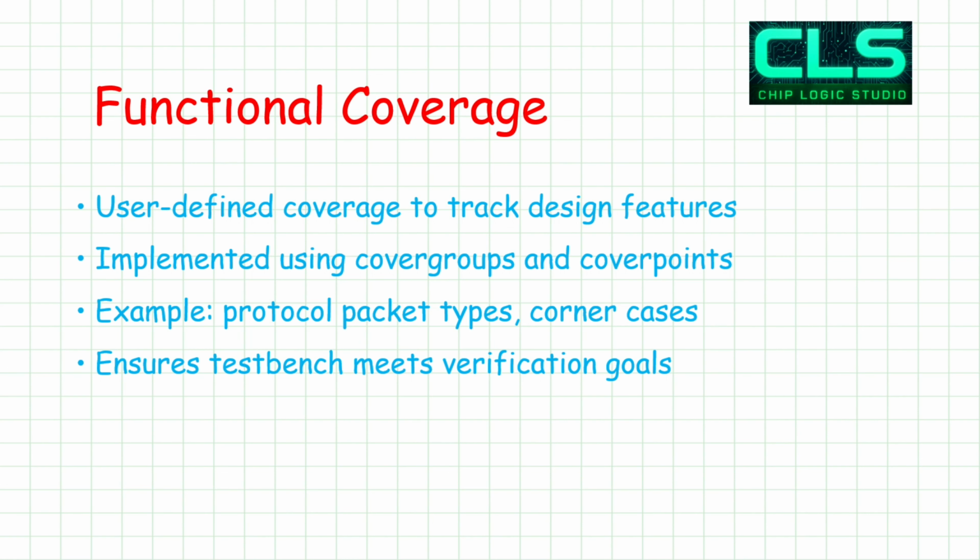All of the packets we send towards our design through our test case scenarios are then checked by our functional coverage to see whether they are covered or not. Also, the test bench meets verification goals. So some set of goals are there. For example, if version 1.1 is there, it says that 93% of functionality should be covered, then the next version should cover 97%. So the target is also achieved with functional coverage.